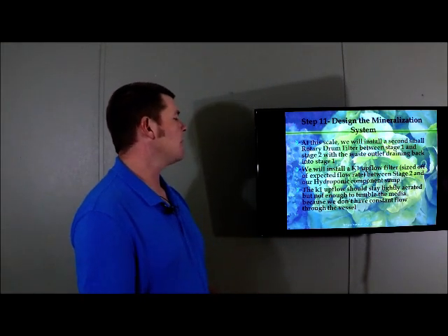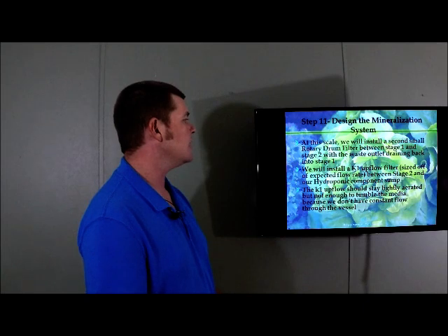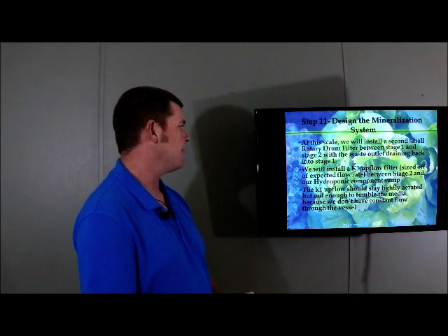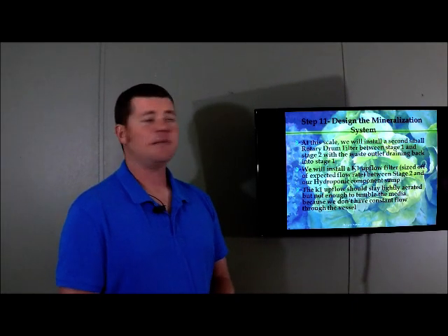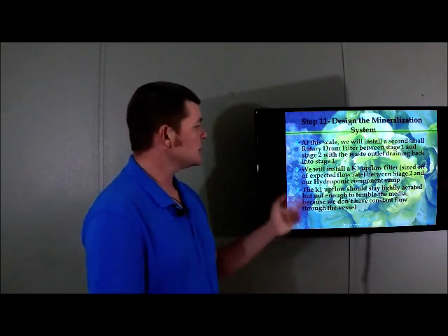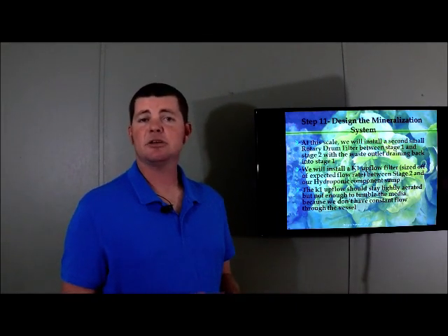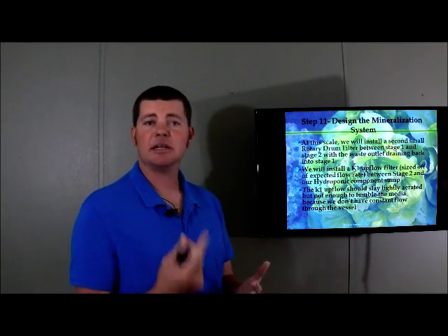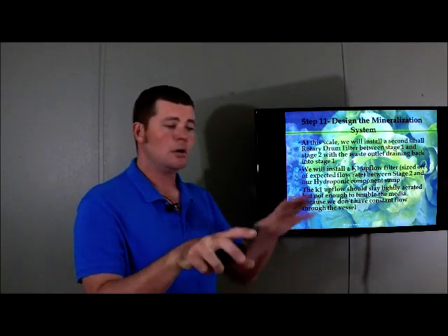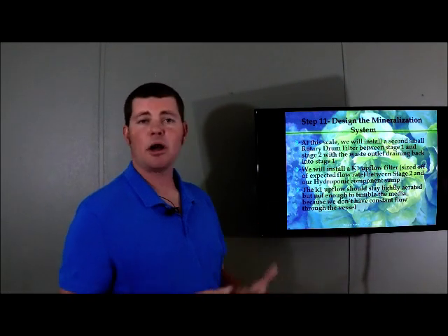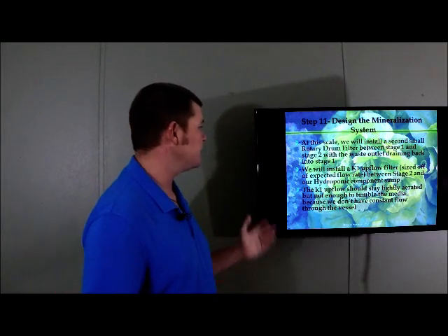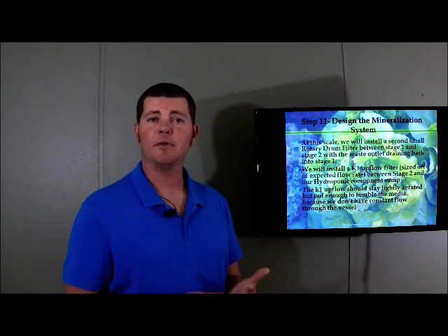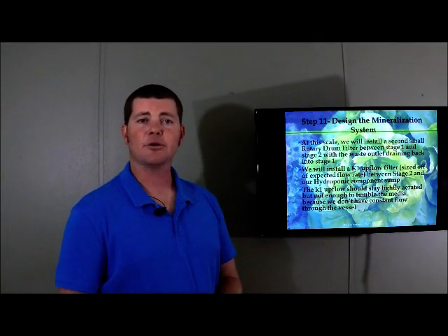We will install a K1 upflow filter sized off of the expected flow rate between stage 2 of the mineralization tank and our hydroponic component sump. Okay, so we've got 15 of these greenhouses. This line is going to flow out and split between those 15 greenhouses into a sump, the central circulating sump between those two deep water culture troughs. And we'll talk about the sump in a few more slides. But this is going to flow out. What I would suggest is just send it through one large K1 upflow before you split the flow and go to the 15 greenhouses.